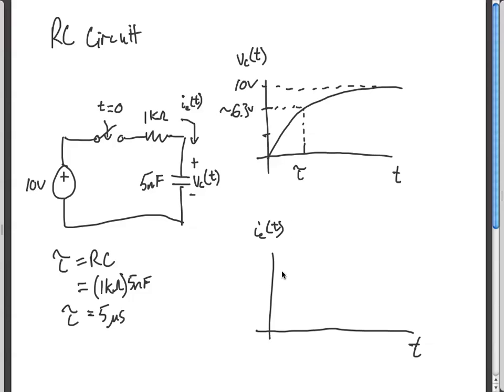When it's empty, which it is corresponding to this graph right here, how does it behave? What's its impedance? What does the cap behave like when it's not charged at all? A short circuit. That's right. Its impedance is 0. So if its impedance is 0, and this can be approximated as a wire just connecting right here, then the current should be 10 volts over 1 kilo ohm.